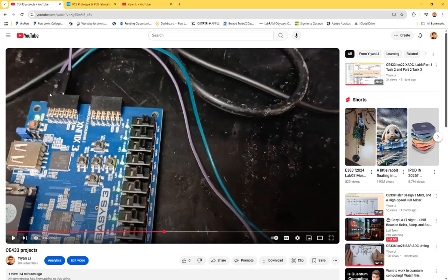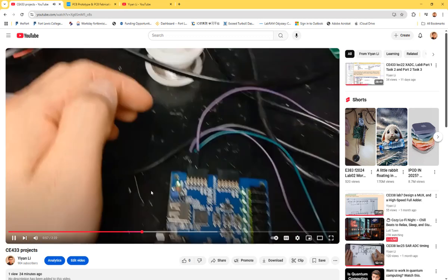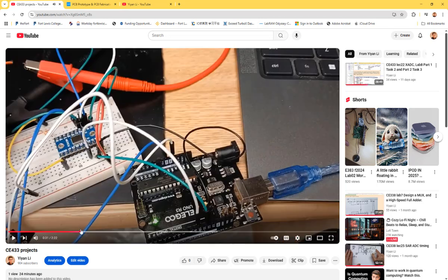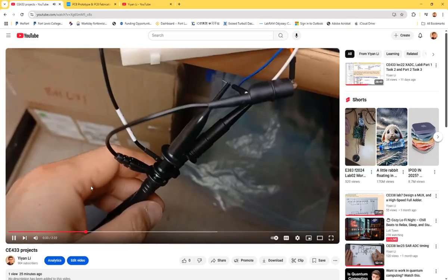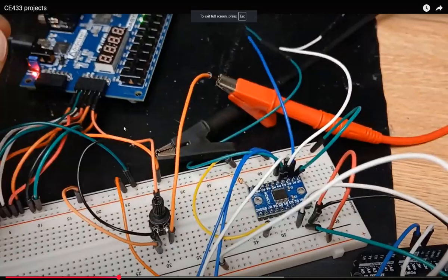So it's basically from the top three pins over here. Display analog voltages. Okay. Another thing is the XADC looks at the signal. Yeah, I have two, I just did it, so I don't have snapshots. So I have to pause the video multiple times. So you can see the 3.3 volts can be connected to this pin, and there's a ground. It's providing a universal ground to the ground rail on the breadboard, and all the other channels should be grounded.